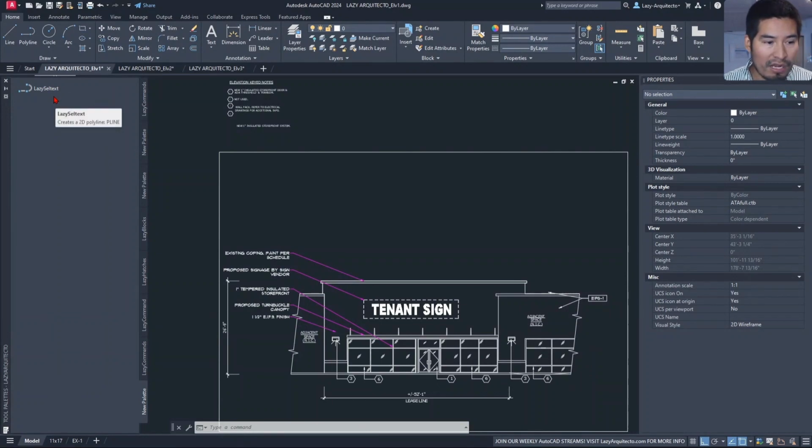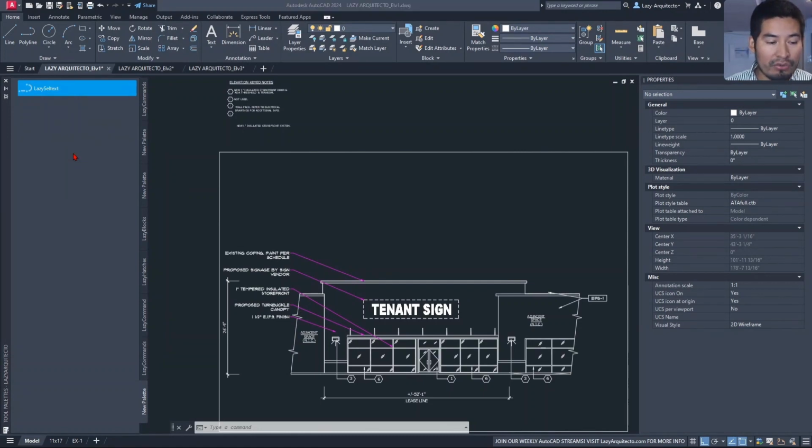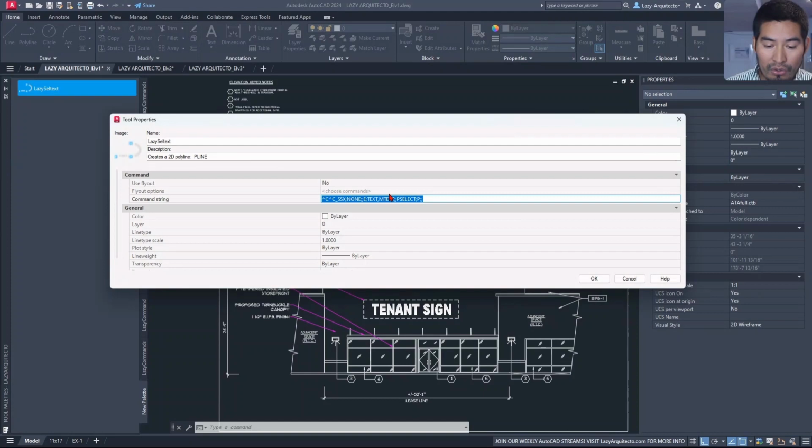And again, to go back to the question, let's right click over here. We already created this macro, right? We already created it, so that's why we have the code right here. Anyway, the problem that she was having is with this part of the code, and probably if she's having this problem, maybe there are more folks that are also having the same issue. She's saying that P sometimes stands, depending on the AutoCAD version, for the pan command. So what we can do is maybe utilize an alternative option right here, right?